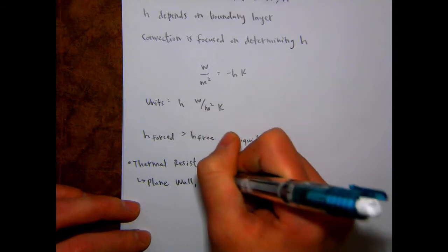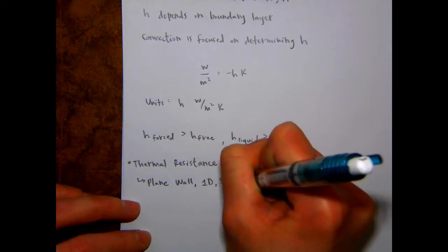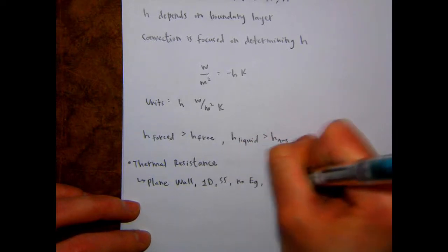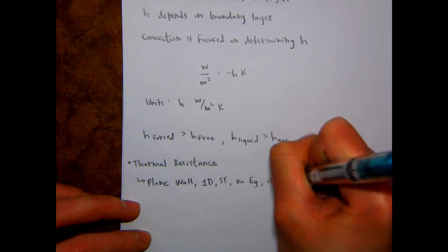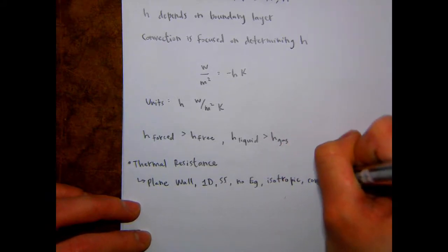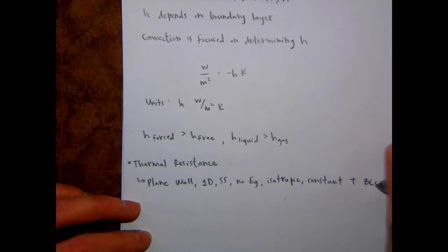And let's write down all these assumptions that we made. 1D, steady state, no energy generation, isotropic, constant temperature boundary conditions.